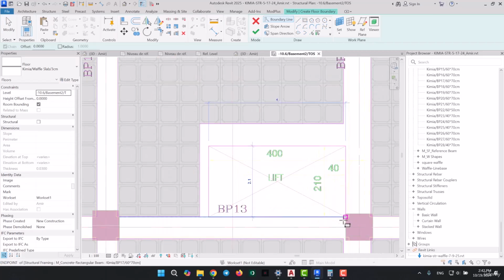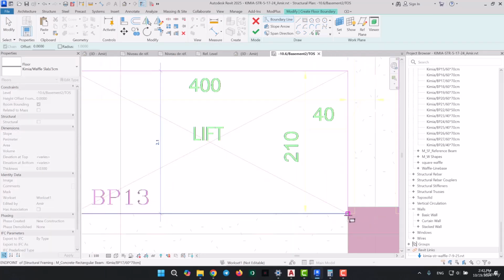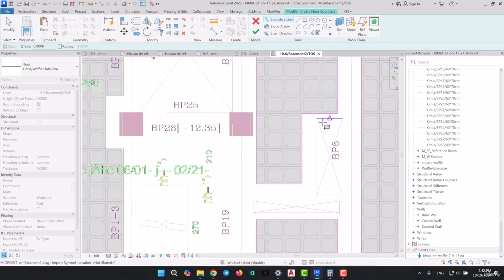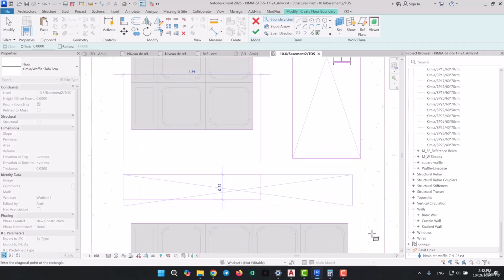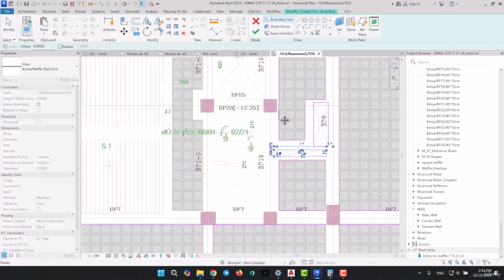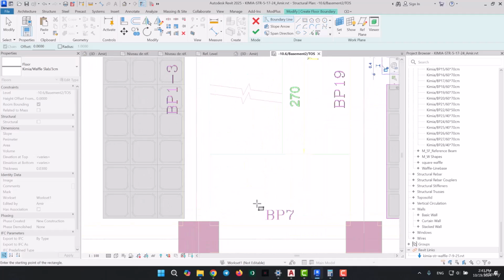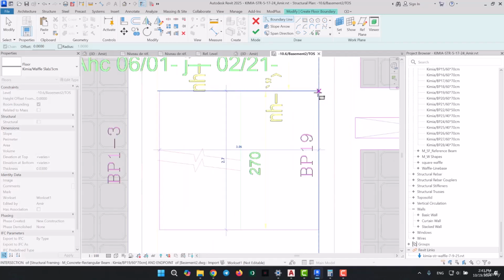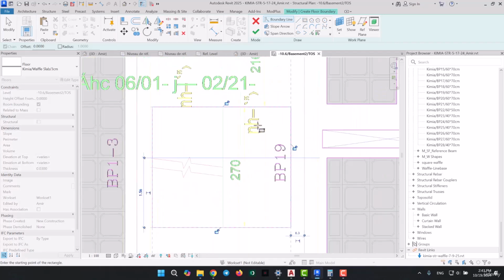Do you see how easier this way is? So don't waste your time drawing everything all over again. If you just follow what I showed you, that'll definitely speed up your process big time. So for example, I'm going to exclude these ducts because clearly we don't need slabs on them. So you'll just have to exclude some parts, as well as these staircase boxes. Not to mention that the staircase footpaces do have the slabs on, so for example, you're going to have to exclude here to here. Something like this.